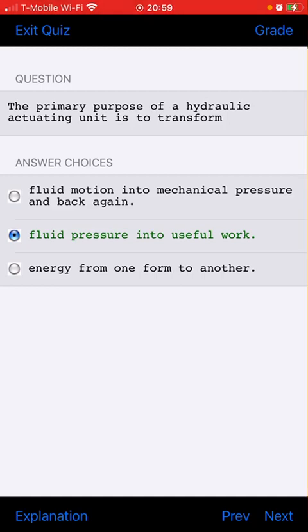Repairs or splices involving stringers on the lower surface of the stressed skin metal wing are usually what? Permitted, but are normally more critical in reference to strength in tension than similar repairs to the upper surface.